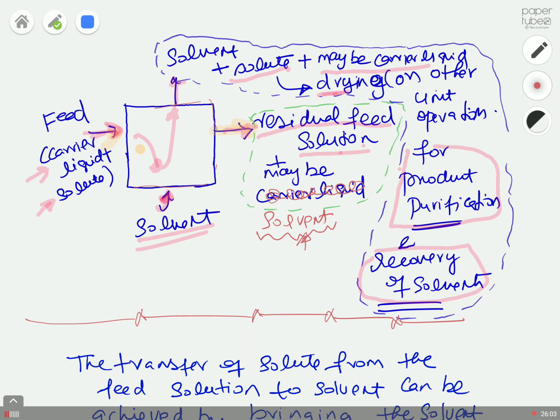Imagine you are extracting something using 10,000 kg of liquid. You cannot dispose of that solvent after extracting. You have to reuse that solvent to save a lot of money. That's how recovery of solvent becomes really important. And for recovery of solvent, we go for other techniques like evaporation followed by condensation, or distillation. So whenever we talk about extraction and the money involved in liquid extraction, you should think about all these factors. That's why I made this diagram, for a reason.